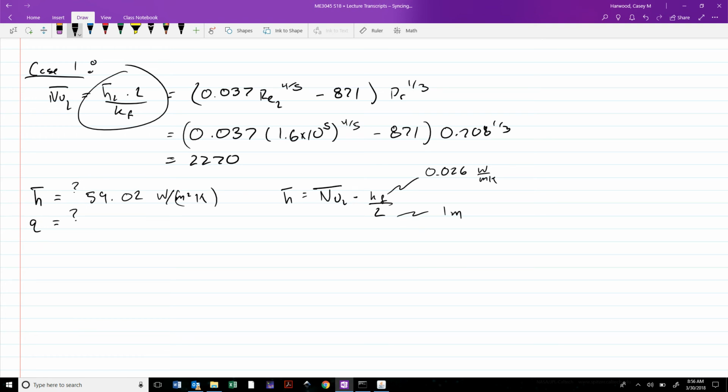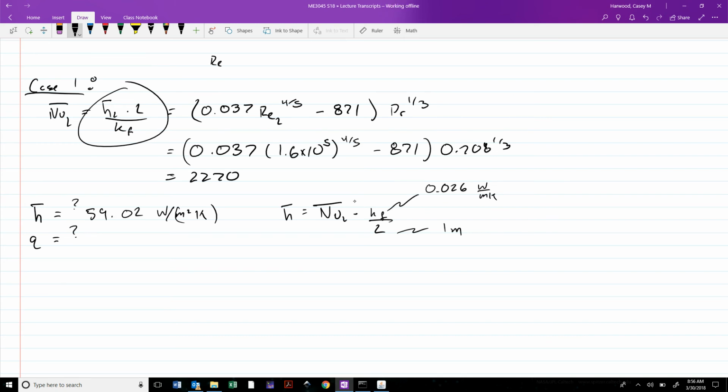How did you determine it was that Reynolds number? Just because that's the Reynolds number based on the length, the total length of the plate. I mean, we know L, we know U infinity. It's sort of like if Reynolds number based on x is the local value of x, then the Reynolds number of the whole plate is just based on the total length of it.